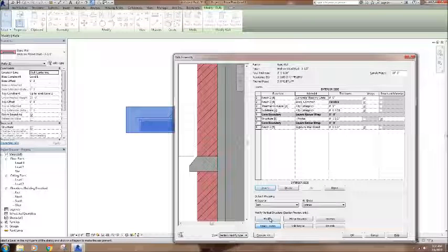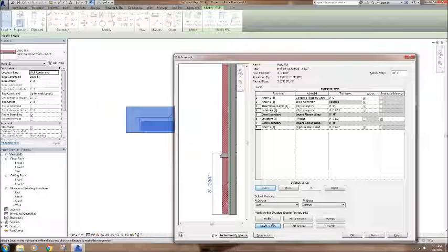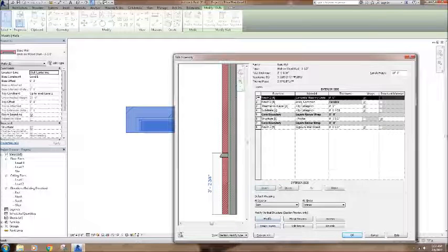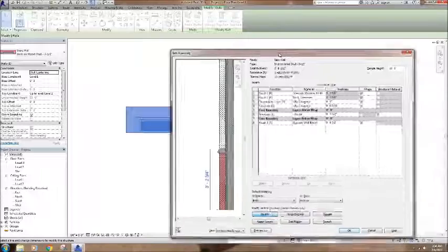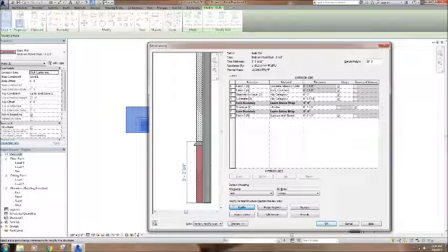And what I need to do is basically select, I'm going to go modify, select this whole unit, and then hit assign layers, and then I can grab the very edge of this and click that, and make sure you do not hit escape when you're in this, and then hit modify. If you hit escape, it backs you out of this entire window. That's what I did just a minute ago when it backed the whole thing out and I had to create the sweep again. You'll end up losing everything that you did. So this is what we call a compound wall. So I have a brick below, a different material above, and I've created a split region here.